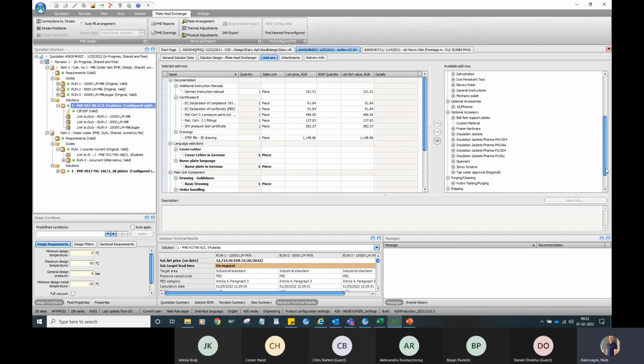But for a food heat exchanger, my normal selection choices are ball feet plates, which are small plates they can place underneath the ball feet on the frame. So you level out the pressure, the footprint on the dairy floor. Some want it, some don't. Again, it adds to the price, but these ball feet plates are relatively cheap.